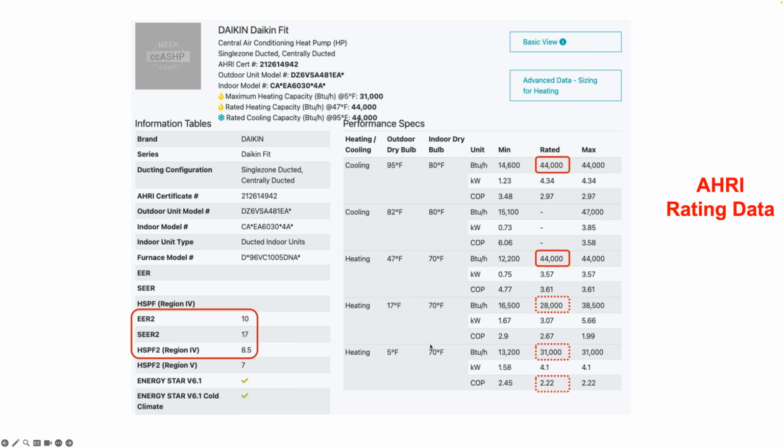And this unit doesn't show it, but there are units that have a value at what's called the lowest catalog temperature, which might be much below 5 degrees and closer to where the compressor actually shuts off, where we need to know what that performance is, because the whole idea of cold climate heat pumps is that you're operating in climates where temperatures get much lower than 5 degrees.